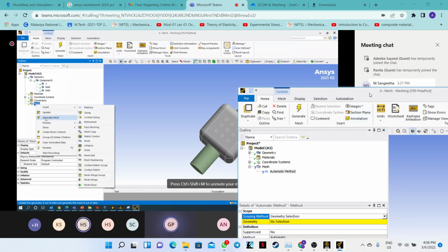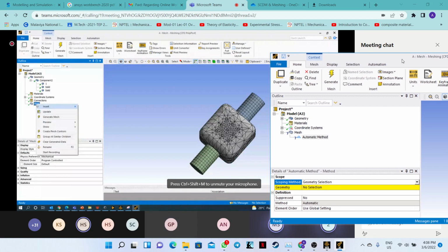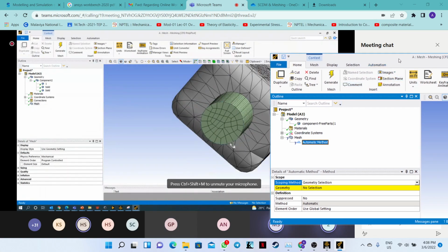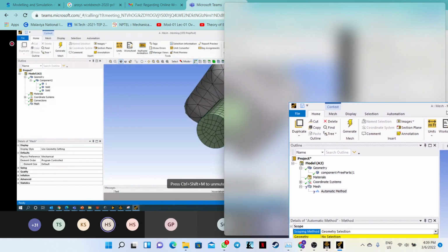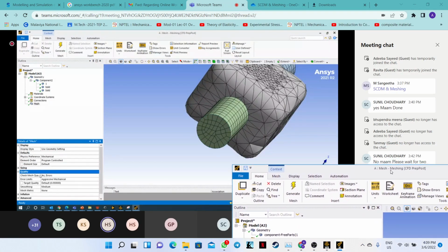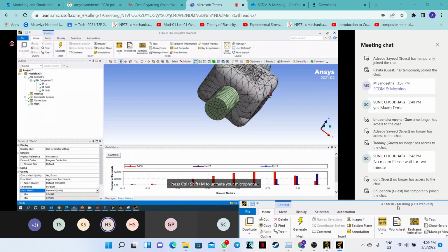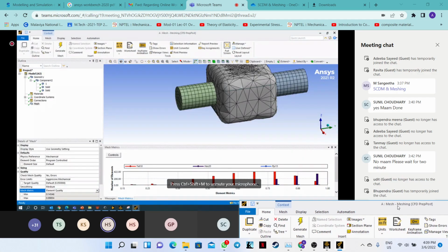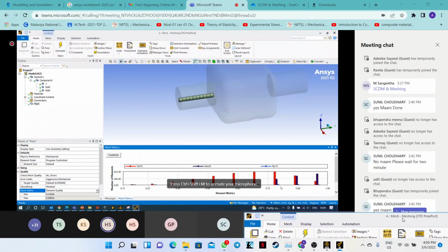Let's say I want to generate an automated mesh for my geometry. All three components are different for me, right? I don't have to create a sweep mesh for this one separately, because the mesh is already a mapped kind of meshing. When I go to quality and show the element quality, you can see the color indications, blue and navy blue. Blue are mostly poor quality elements near these connective regions. Other than that, whatever elements are created are of good quality.